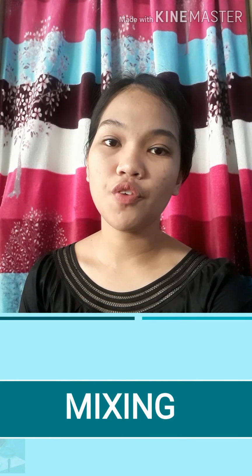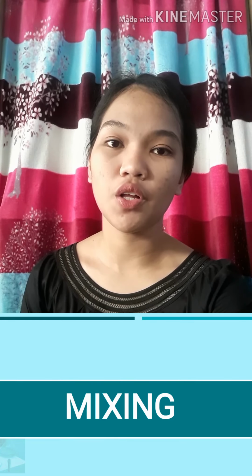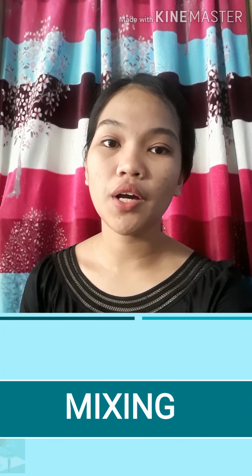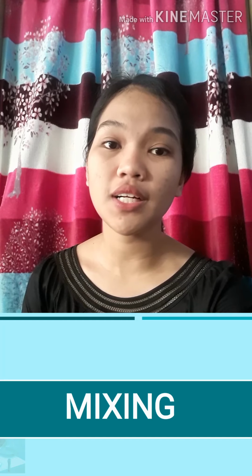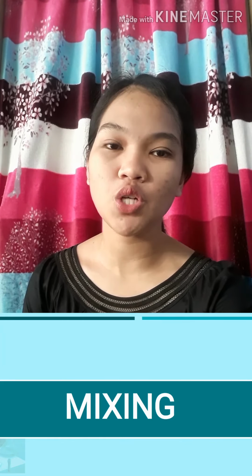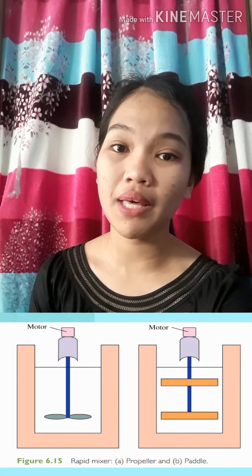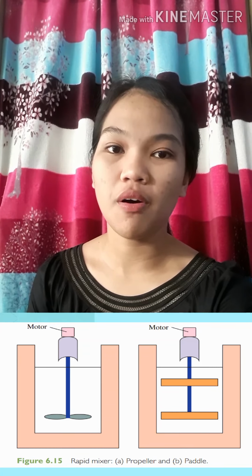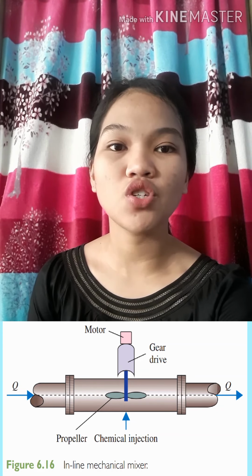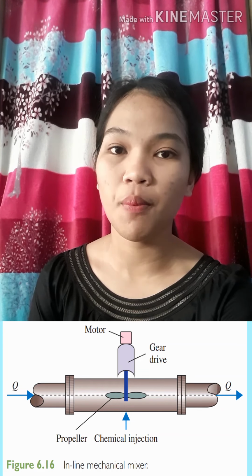Now we are down to our fifth topic, mixing and flocculation. Let's start with the mixing. Dispersing coagulants into the water is a critical step in the treatment process sequence. Mixing of chemicals may be accomplished by turbine and propeller mechanical mixers, over and under baffling, inline mechanical mixers, inline static mixers, and by injection into the suction intake of the pump.